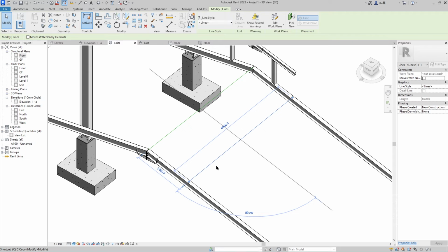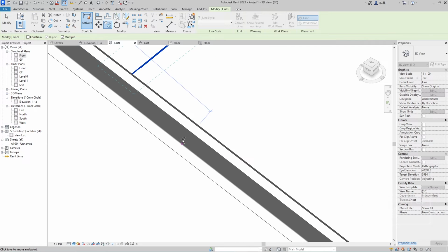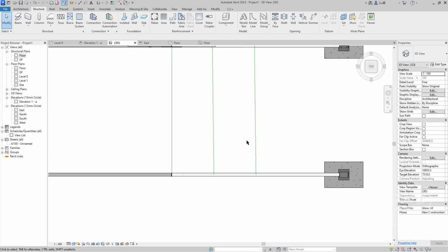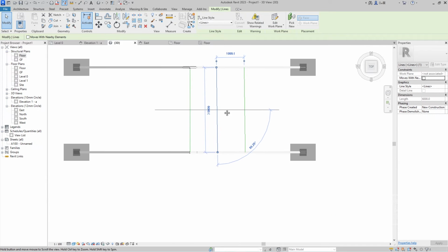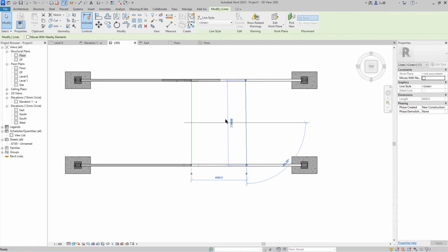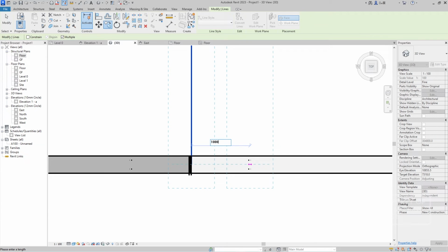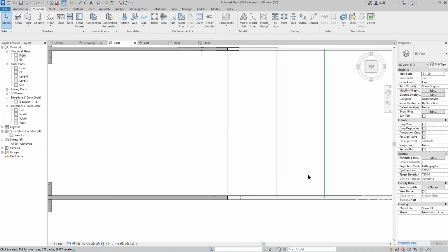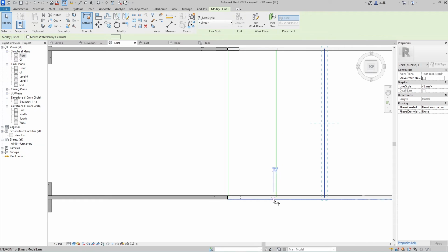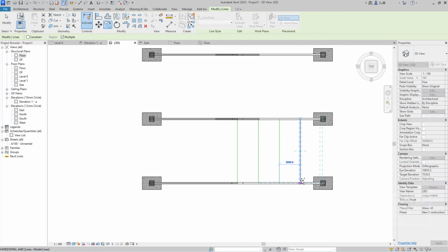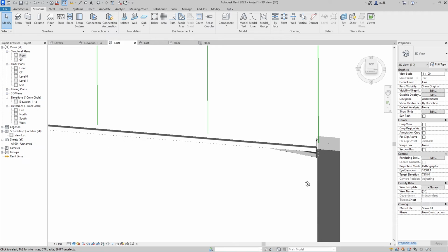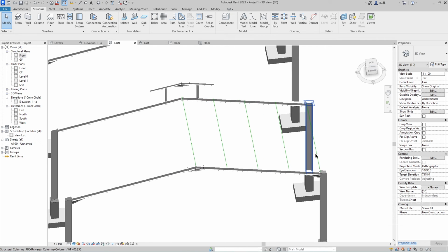Need to move it, so you can see the line now created on the surface of this beam, and we're going to create a similar one like this. So we just need to copy it and then choose the center point, go to here, to that, and copy it again. Yes, this line is actually not a clear one, so let me just delete it. We try to copy it again, center point 1,000, and then to 1,000 again. Alright, and then CO again, copy it to here, and the last from here to here. Alright, so as you can see here, we have successfully created the manual bracing system for our warehouse.